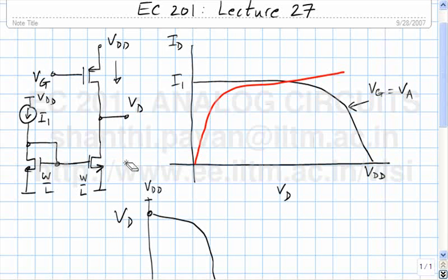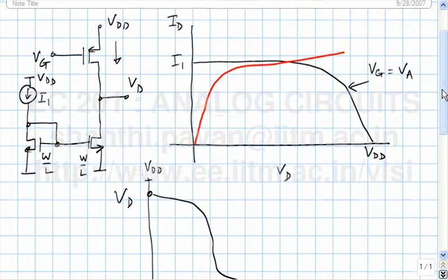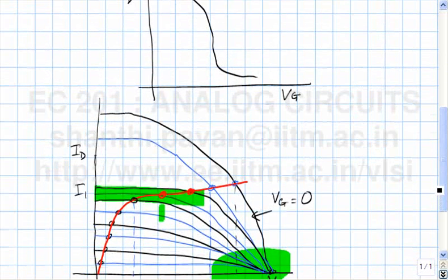How much source gate voltage do you need for the PMOS transistor to conduct? You need Vt. So the moment the Vg goes to VDD minus mod Vtp, the PMOS transistor will get cut off. So if the PMOS transistor is cut off, what happens to the current? The current is 0. So what will happen to the output voltage? It will also be 0.